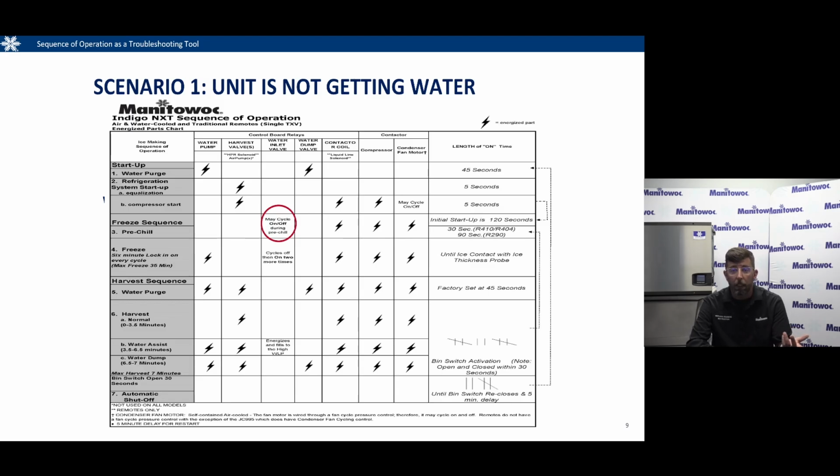So if it was me, what I'd be doing is turning the machine off, unplugging the water probe, and seeing, does it stop sensing now? Oh, it does? I've got a false sensing water probe. Maybe some crusty scale buildup on those 3 sticks. Clean it all up, dry it off, pop it back in, and you're off to the races. Or maybe it's a shorted probe that can't sense.